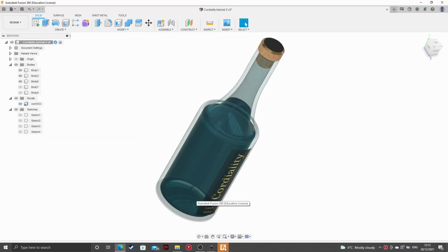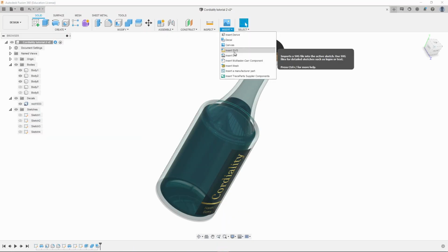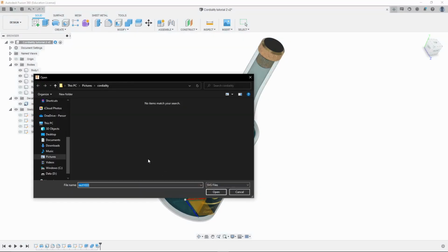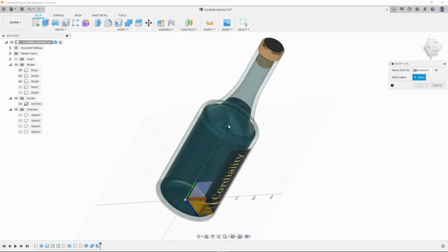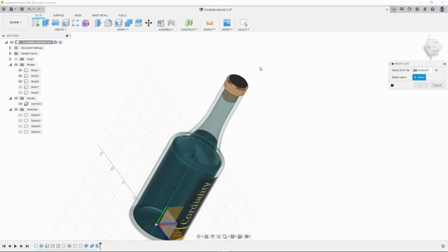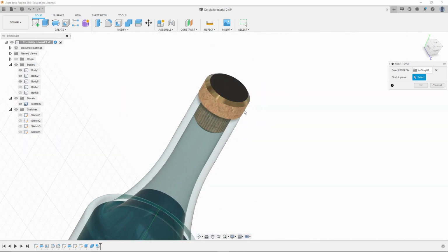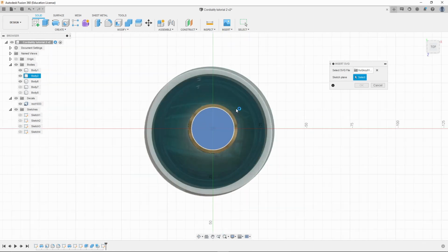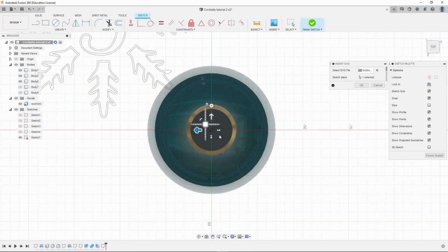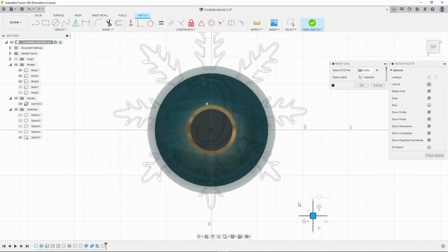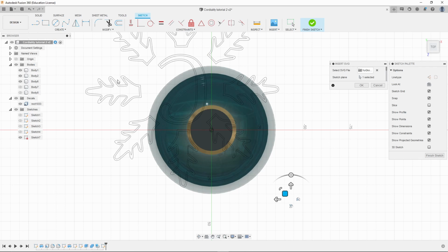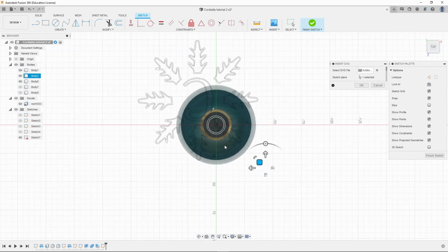Now I'm going to go into Fusion and I'm going to insert that SVG from my downloads. Where are we? So there's the file. Open. And you'll be able to tell whether this is a file that's suitable, because if not, this will be really laggy. When you put things in and you try to move them about like this, what I was finding earlier when I was using a different website was this was really glitchy and laggy, and it was because these edges had so much detail and so many tiny little shapes that we didn't need that it slowed down the program.